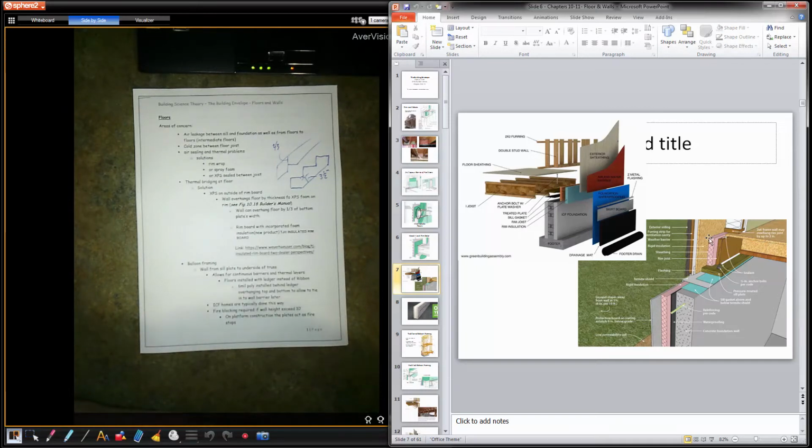But again, taking care of the vulnerable areas. You see a bead of silicone or sealant here. A lot easier to do that while you're framing the floor before you put the plywood down. And put a bead of sealant there. Try and get in there later, it'll be hard to get to do a good job. You won't be able to see what you're doing. Where if you did it from overhead, fairly easy to put a bead of caulking there. So our acoustic caulking would be the best product there.